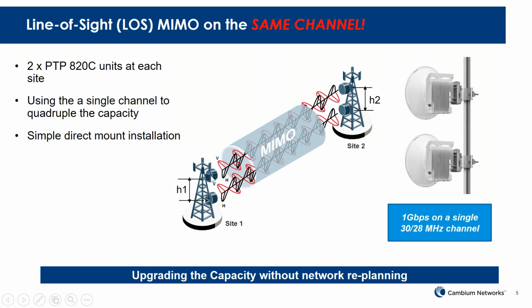So you see the first radio is beaming out 2 streams, a V pole and H pole. That's using XPIC. And again, the second radio link is also another XPIC. But then to XPIC, using phase separation, you achieve 4x4 MIMO. The installation is a simple direct mount installation.